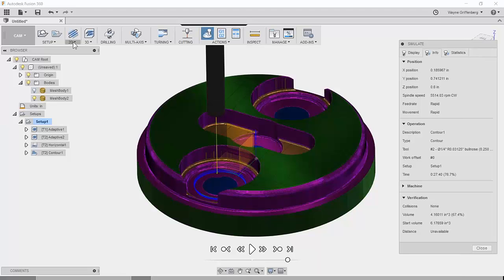But I just want to mention that because it's always good if you can get the information as close as you can to an original source. So if it's a choice of a SolidWorks file or an STL file, you should always get the SolidWorks file because, as Al mentioned, if you want to do any 2D machining, it's nice to have the edges from the model. So I just wanted to point that out.